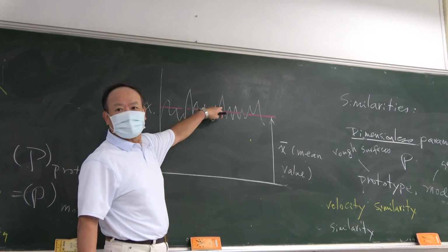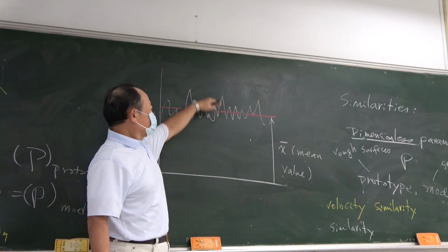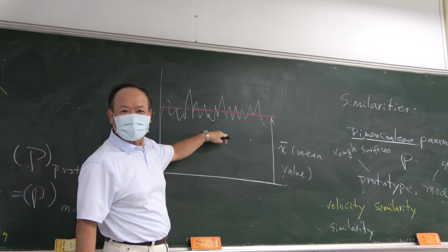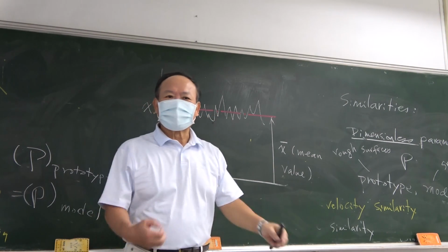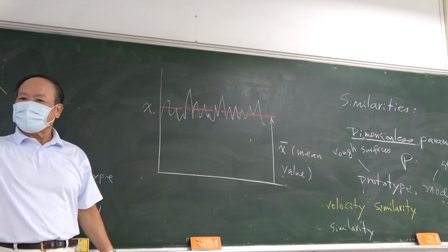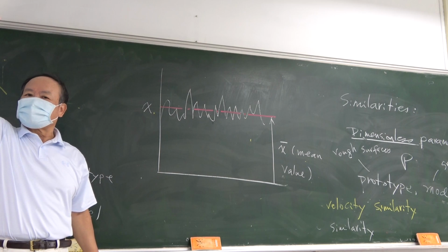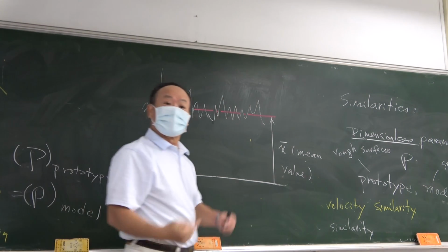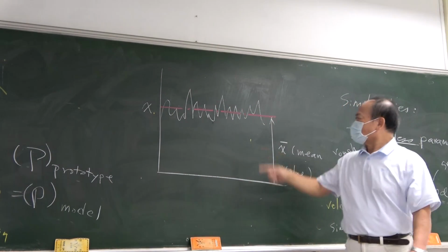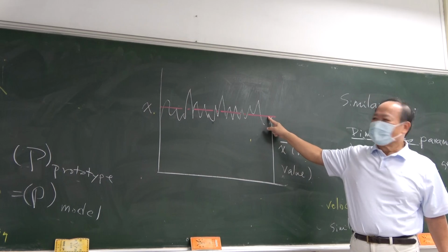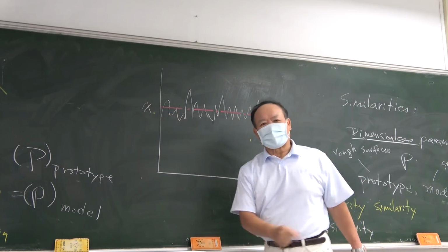The volume or the area above this mean line and below the mean line are equal. So the central line, this mean line, is where the volume or area above it equals the area or volume below it. It's very easy to use a computer to determine this value if this surface profile is available.